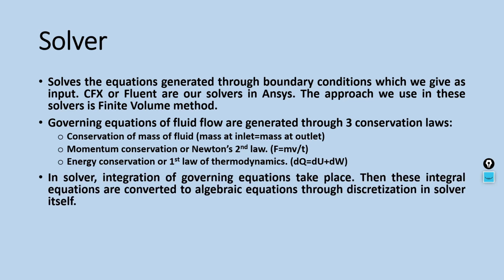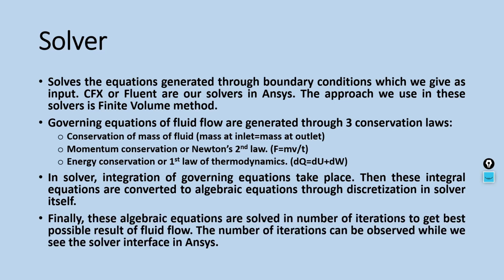Now the integration of governing equations takes place in solver. After that, the integral equations are converted to algebraic equations through discretization in solver itself. And finally, these algebraic equations are solved in a number of iterations to get the best possible result of fluid flow. The number of iterations can be observed while we see the solver interface in Ansys.